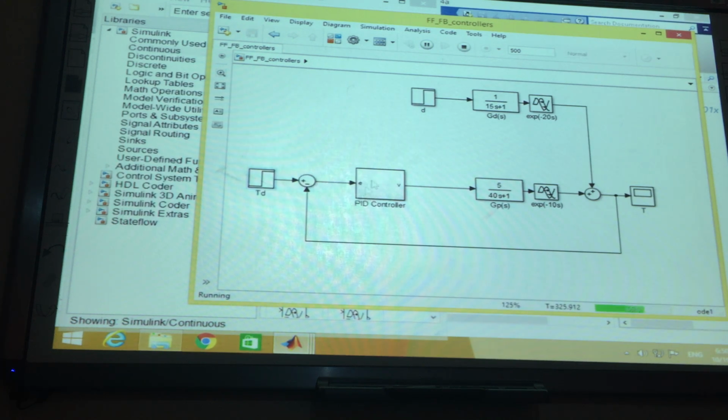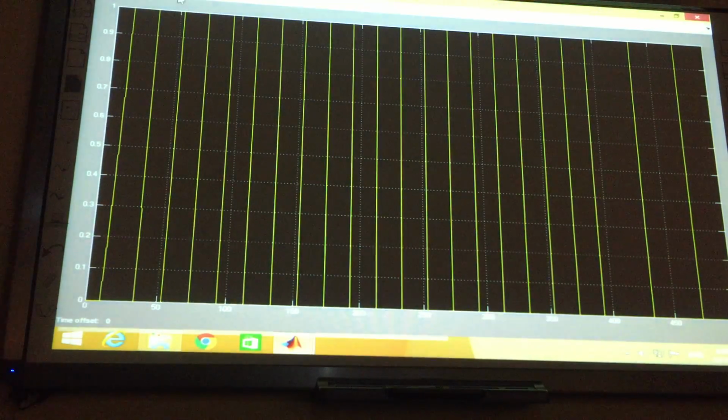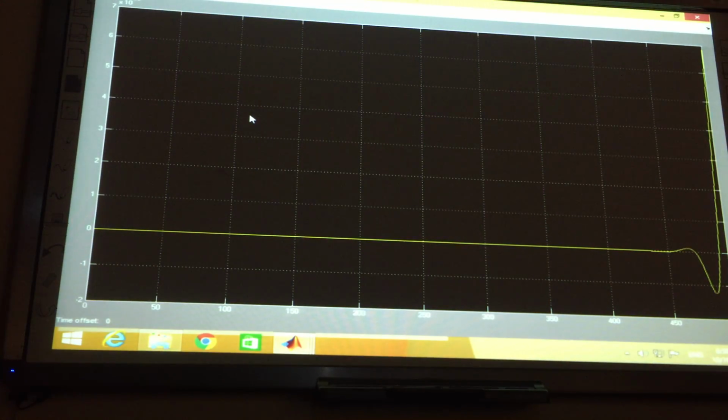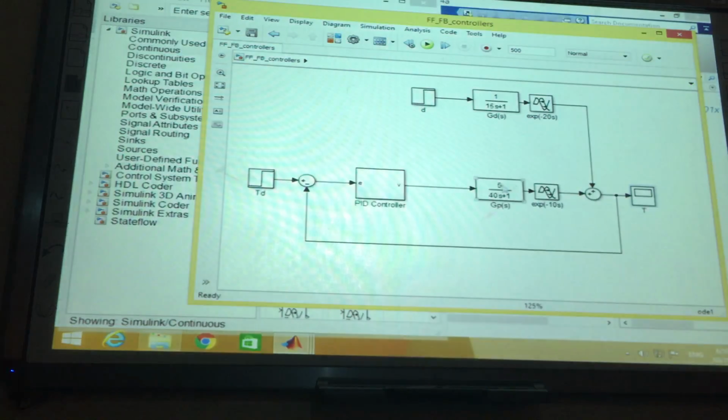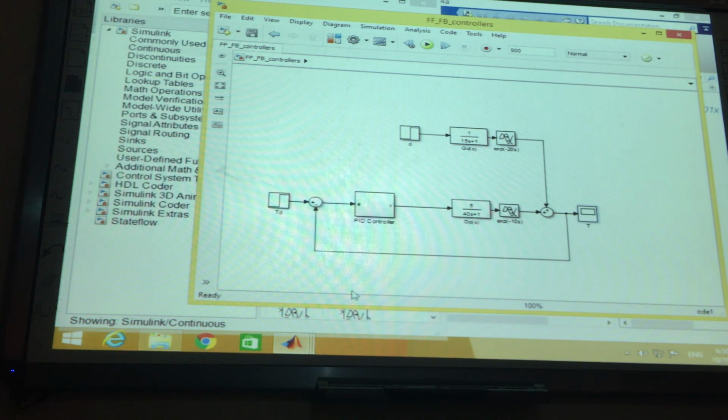Still, I didn't actually change the PID controller. How can we make the PID controller? Using what, guys? One of the options, using Ziegler-Nichols method, we can tune the KP, KI, and KD, right? But let's try it right now for the current one. As you can see, it's going to go out. It's going to be crazy. Then what should I do, guys? You are not concentrating.